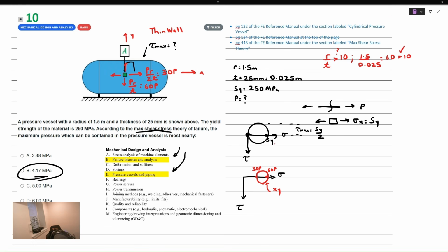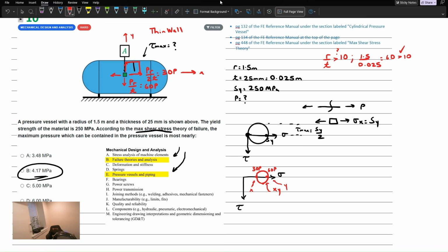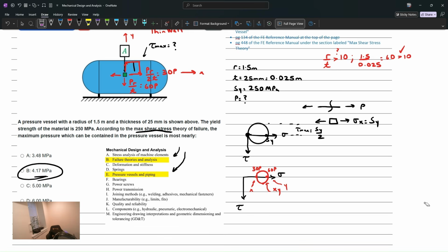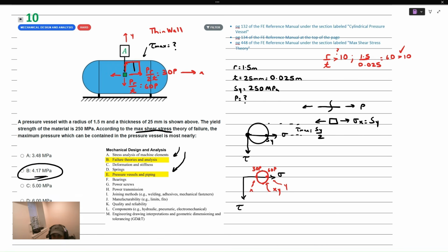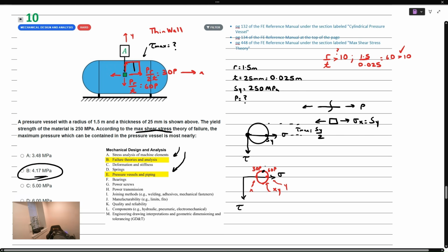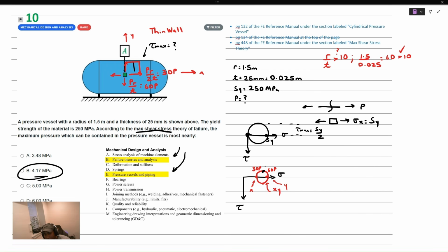One thing I want to note is that you can see that the angle between the stresses on the X face and the stresses on the Y face is 180 degrees on Mohr's circle, but in real life it's 90 degrees here. And that's because all angles on Mohr's circle are doubled. So actually, to get to the max shear stress, we would rotate around by 45 degrees in real life or 90 degrees on Mohr's circle to reach this upper point. But this is actually not our maximum shear stress in the body. This is only considering the XY plane.